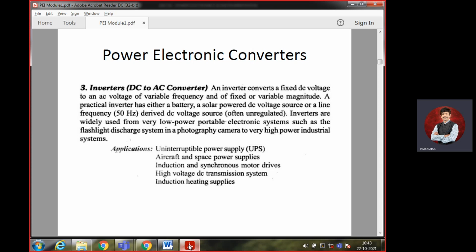Then after T2 I switch off, not applying base current to both transistors. After that, at T2 to T3, I will switch off these two and switch on these two. You can have some more delay also, no issue.